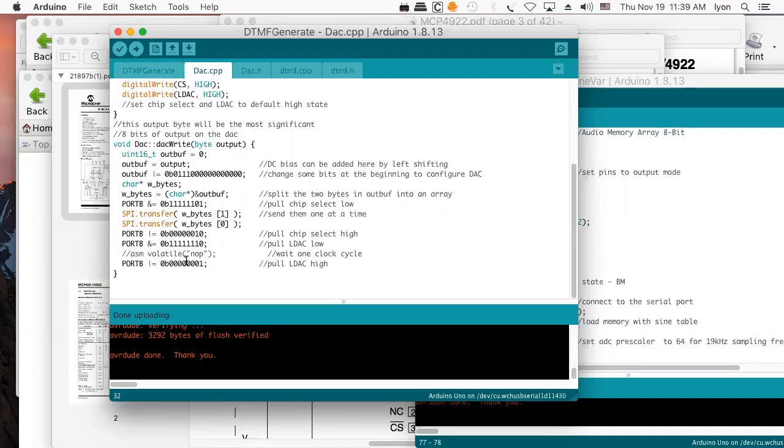When you write, you may be exceeding the time it takes to get a reaction out of the DAC. So you want to load the DAC, and you want to give it a little time to load the next number. That's what this ASM is for. This ASM assembler, and this NOP is actually the symbolic assembler machine instruction for no operation. NOPs on a microchip, I'm not quite sure how many cycles they take, but they're pretty fast.